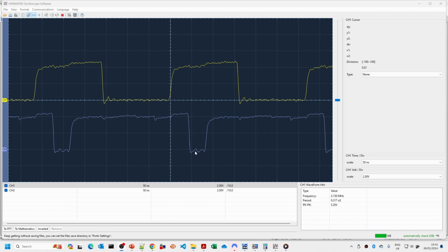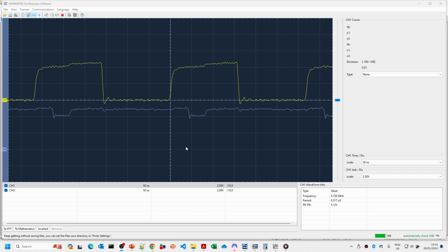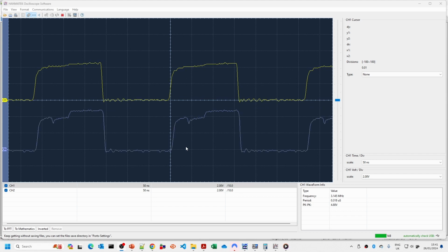At the moment, I think the attribute latch should be around the same time. We might need at some point to change the attribute latch to perhaps be slightly different, but those signals look pretty reasonable at the moment. And then if we finally look at the underline output, you can see that's just high because we've hard coded it to row 14, and all I'm going to do now is plug this into the character clock QC. So you can now see that that will vary with that as well. So it looks like all of the signals there are correct, and so what we can now do is start to look to wire up the other parts of the circuit.